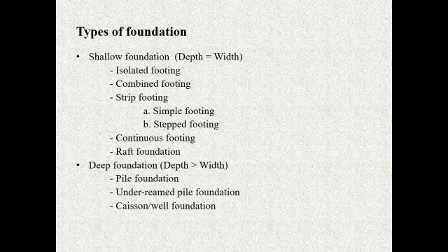When the depth is greater than the width, then the foundation comes under the deep foundation. These types of foundations are used in the area where the soil bearing capacity is very low. And pile foundation, under reamed pile and caisson or well foundation come under the deep foundation category.